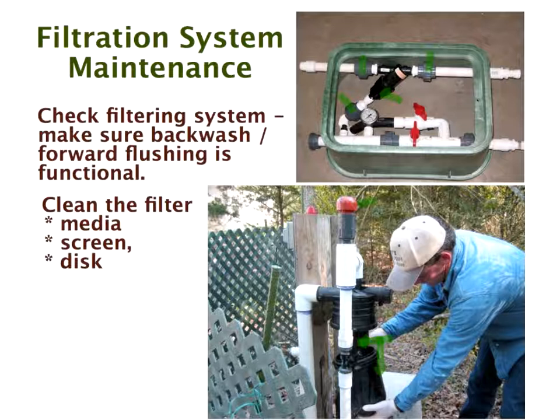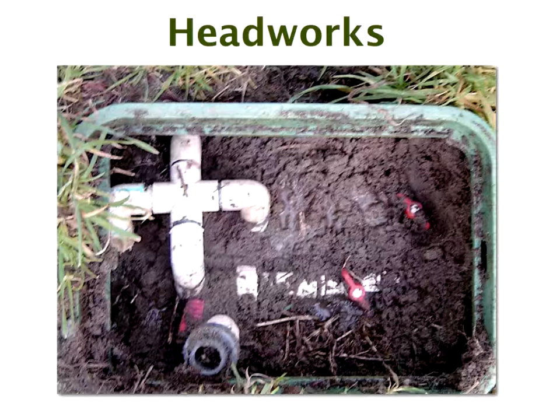And this applies, I mean, you're dealing with biologically active material, and even if the filter's working fine and the pressure drop across the filter's fine, I still recommend that at every O&M visit, whether it's biannual or annually, that be done. It is simple enough to do, and it's going to ensure good operation for the next year or 6 months. Okay, now here we've got one.